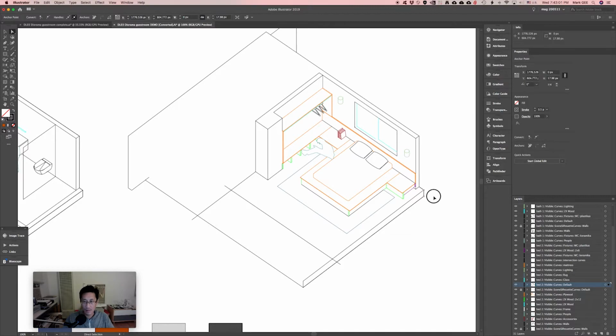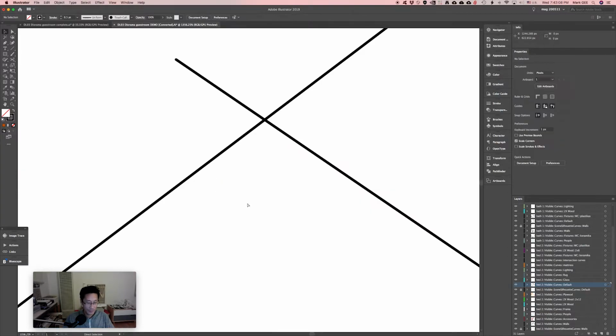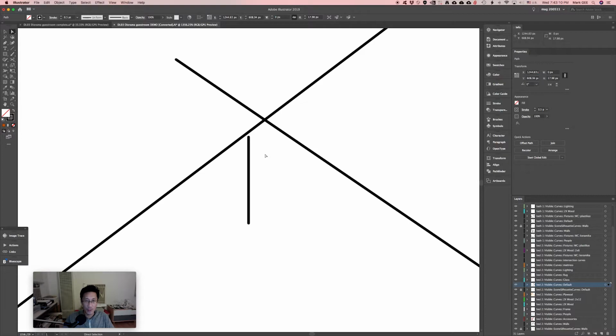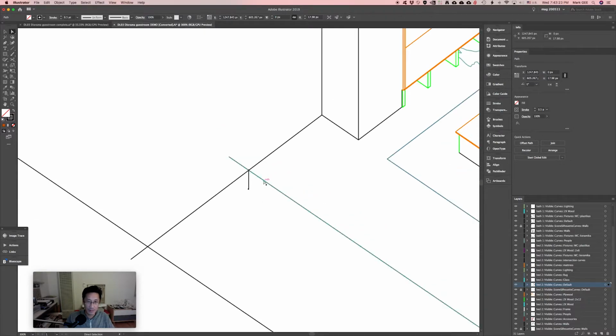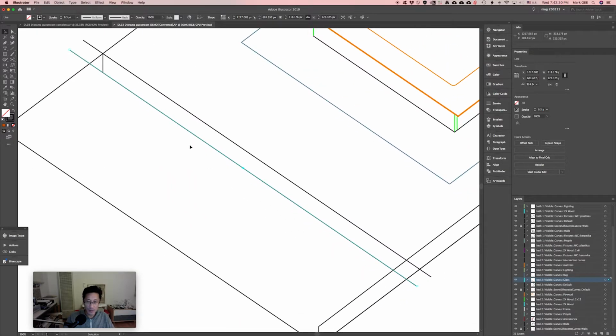And I'll take this line with the black arrow, select it, copy it and paste it here, switch to the white arrow immediately, grab the anchor point to move the whole thing, and try to get the intersection. For some reason, Illustrator was not letting me find the intersection, but that's okay. The Shapebuilder tool will be able to figure it out. Copy that, and now we're creating the section cut through the floor slab here in Illustrator.